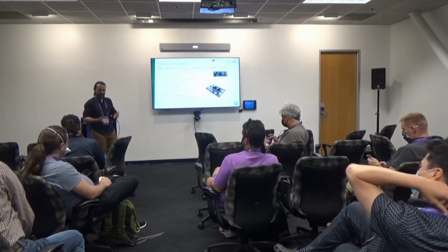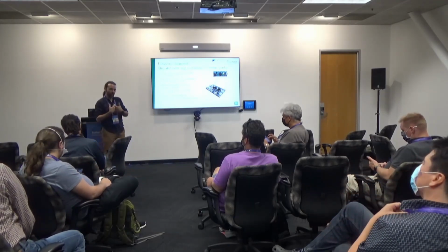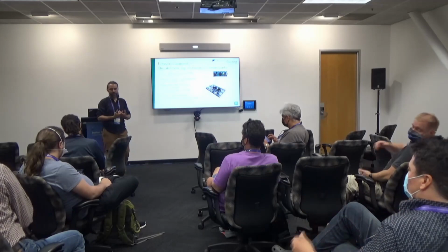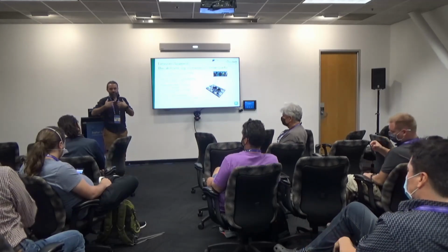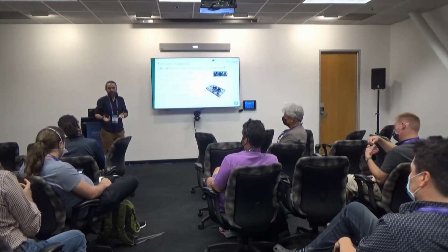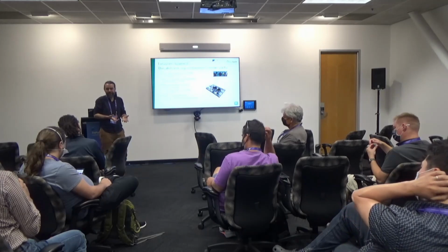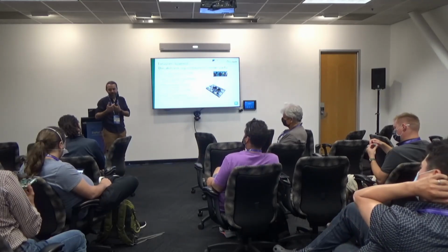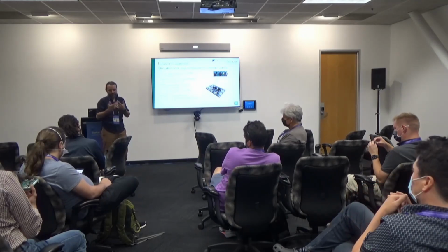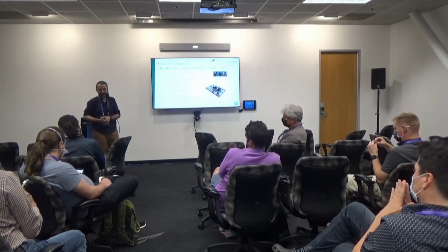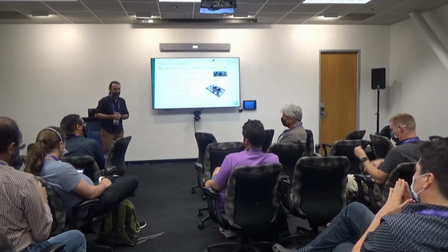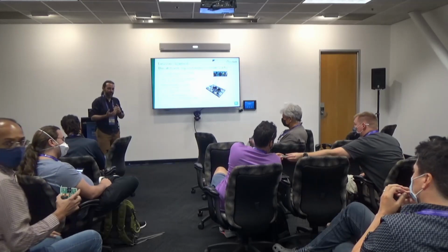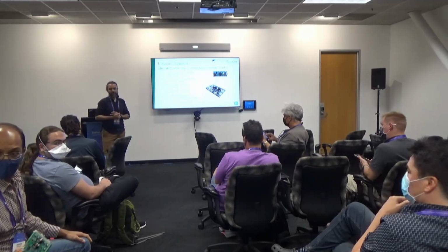And FPGA does not really provide you that nice ergonomics of coding. I mean, people may disagree, but coding with VS Code and PlatformIO and in C is way more accessible for power electronics folk, who don't really like to code in the first place, than going through VHDL and some other arcane way of coding something. It's a lot cheaper too. It's an ergonomics issue.